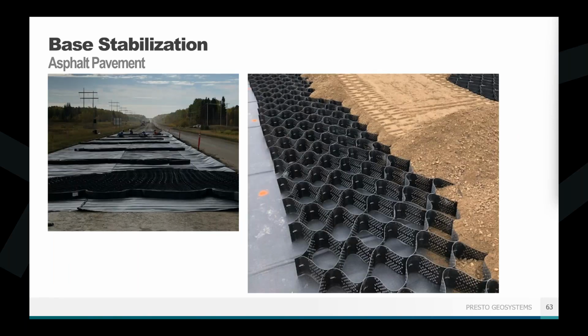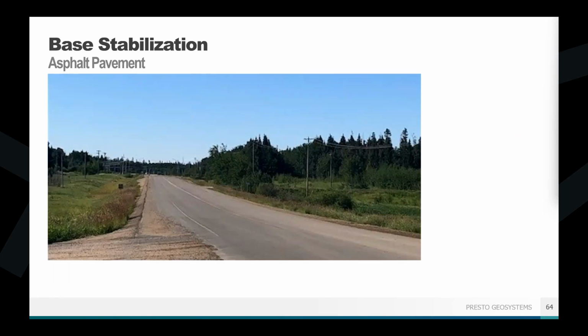And here you can see how that is laying down. Pretty standard, everything we've talked about. That geotextile goes down, the GEOWEB panels on top of that, filled in with the stone, and then you pave directly on top of that. This picture is about 7 years of service life with the GEOWEB panels underneath it.